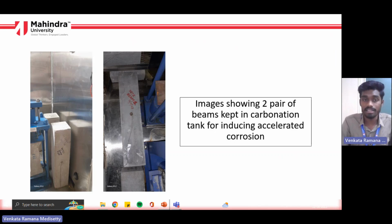accelerated corrosion. As my title said, I would be carrying out a comparative analysis of these three sets of beams, where I test beams at their fresh state, I mean the flexure test at fresh state for the first set, and then for set 2 I'd be testing after 20 days of carbonation. These beams would be put in carbonation for 20 days, then taken out and tested for flexure, and then 36 days of carbonation as such. This is how beams are put in carbonation after PZT is bonded on their surface successfully.